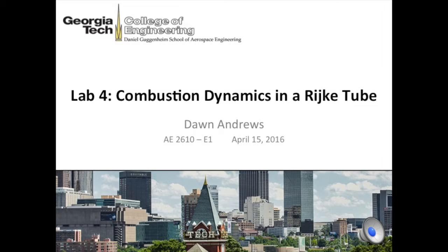On this last slide, the conclusions of the experiment are as follows. We were able to demonstrate the Rijke tube's ability to produce sound from the pressure waves caused by heating the air at a quarter length from the bottom of the tube. And we were able to justify that this was the ideal placement by analyzing the trends in the frequency and amplitude charts and by comparing it to the ideal calculated value for the tube's frequency. We also looked at the relative phase angle calculations and saw how the standing waves were stronger or weaker based on the location of the heat source. Finally, we were able to calculate the flow rate of fuel into the tube in order to understand how the rotameter functions, and also that safety was key to this lab.